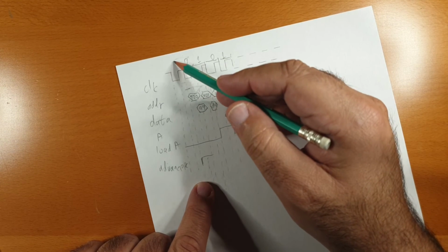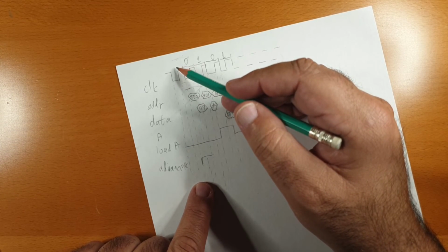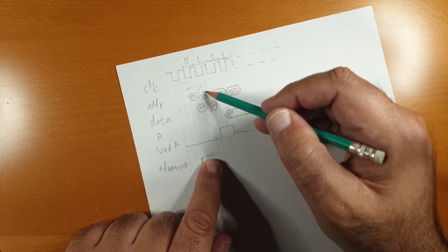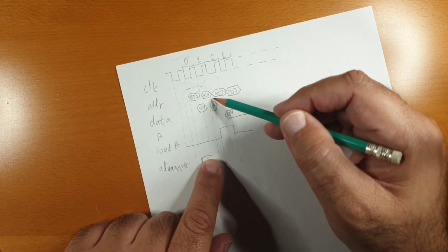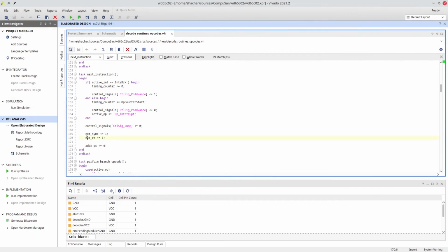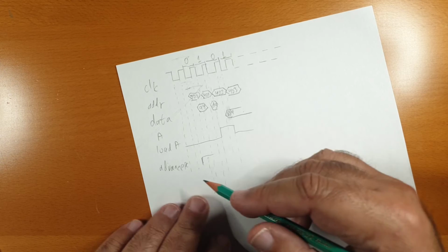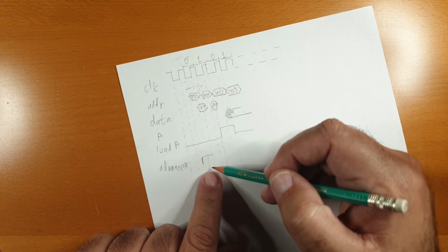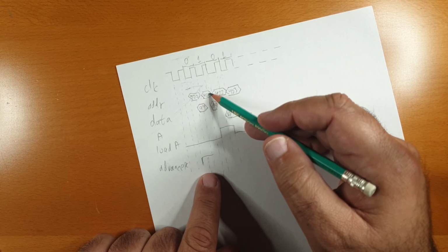Again, remember this runs in the cycle before our opcode begins, which sets the advance PC for when cycle 0 arrives, which sets the program counter for cycle 1. Less confusing, we set the sync signal high. The sync signal is an external signal leaving the CPU itself that tells the outside device that we're now in the fetch cycle. It allows single stepping by cycling continuously until the next opcode arrives. Of course, in our case, the advanced PC needs to remain high because as we're fetching the first instruction, we already know that we'll be in the second one.